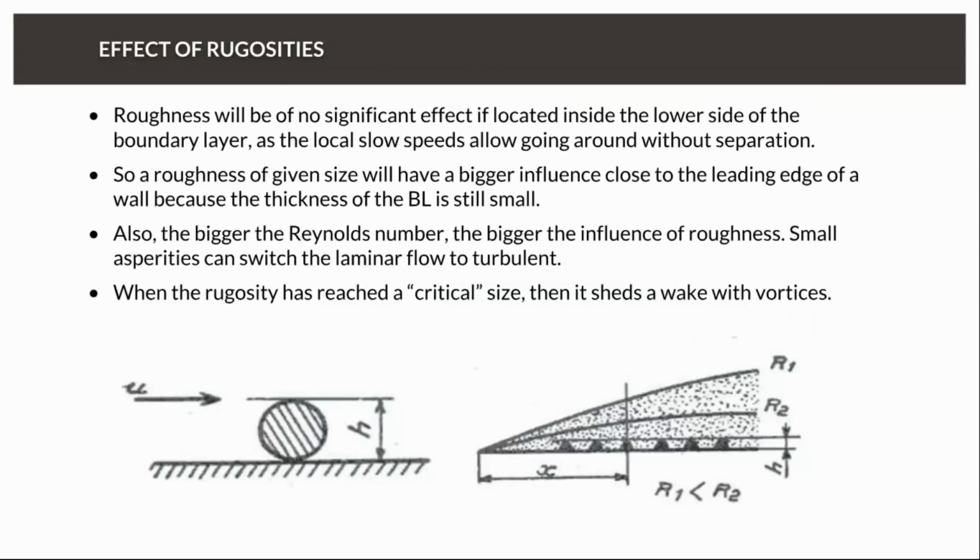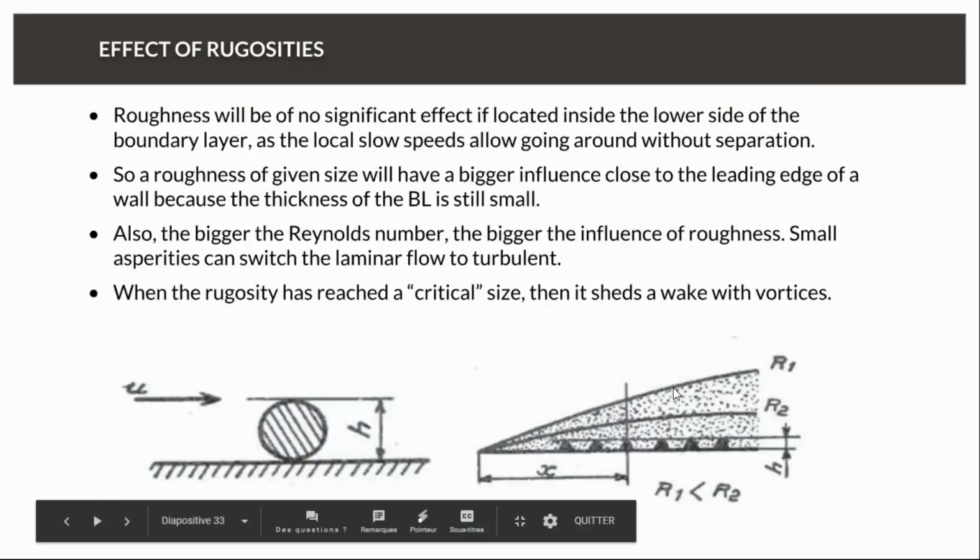And just also the quality of, if you build cars, the quality of your cars, there will still be a small effect of this viscosity. So it's always important that your roughness, your screws, the quality of your surfaces are well made enough so that the disturbances are small compared to the boundary layer thickness. If they start to be big, then you will create vortices, you will create losses, and you will normally increase your drag.